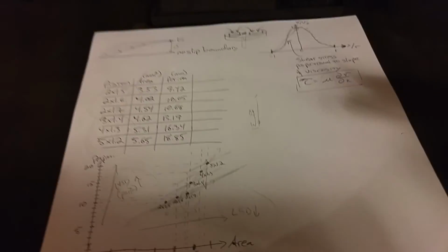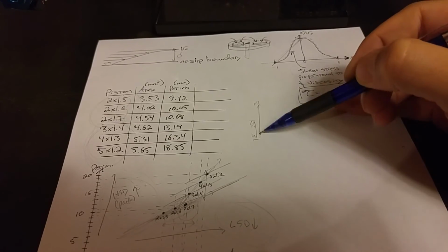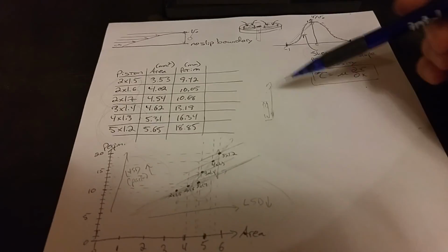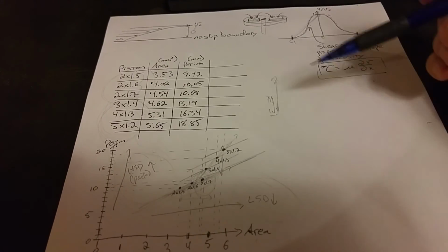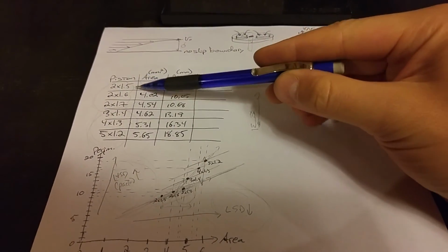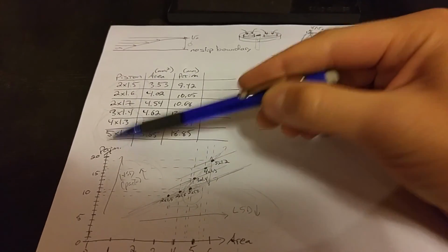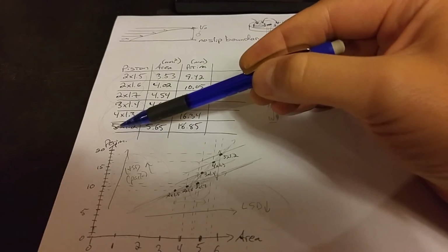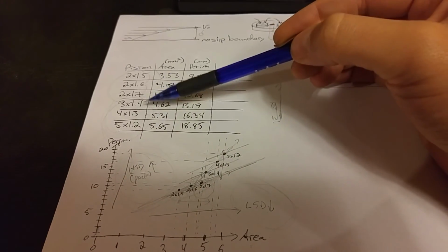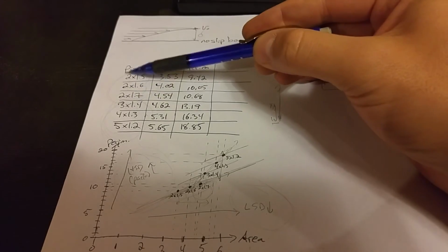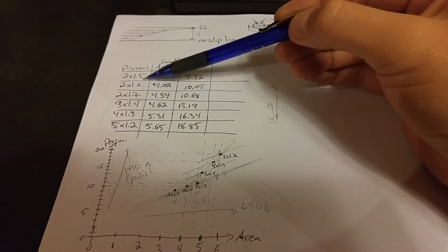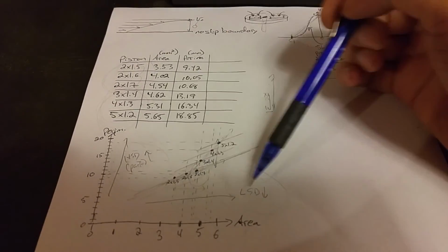Well then maybe I can increase the amount of droop that the suspension has so I get more suspension travel. But if I increase droop, I'm increasing weight transfer from side to side and forward to backward during cornering and acceleration and braking. So there's some kind of compromise that you'll have to make on an outdoor track. But I want to give you a sense of, just very basically speaking, what it means when you change the piston hole size and the number of pistons. Generally speaking, more pistons give you more pack, and at the same number of pistons, as I change the piston hole size, I'm modulating the low speed damping.